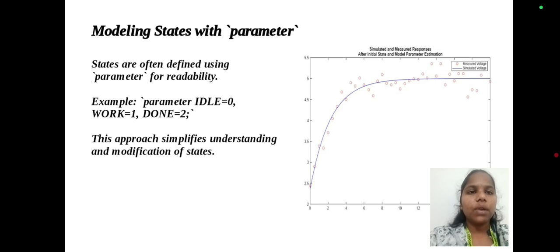Modeling states with parameters. States are often defined using parameters for readability. Example: parameter IDLE equals 0, WORK equals 1, DONE equals 2.